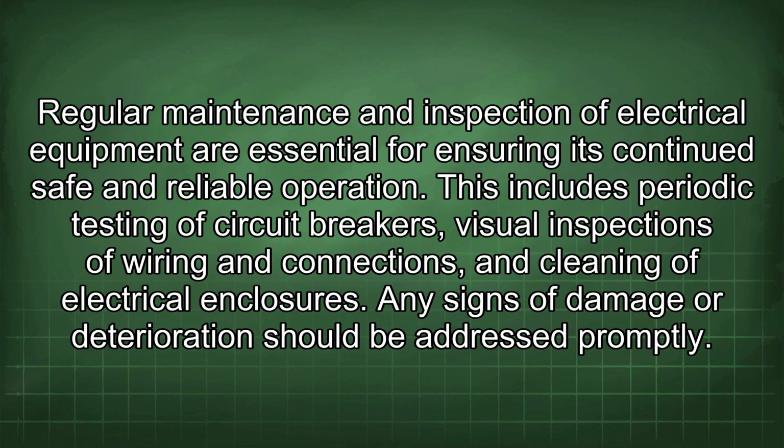Regular maintenance and inspection of electrical equipment are essential for ensuring its continued safe and reliable operation. This includes periodic testing of circuit breakers, visual inspections of wiring and connections, and cleaning of electrical enclosures. Any signs of damage or deterioration should be addressed promptly.